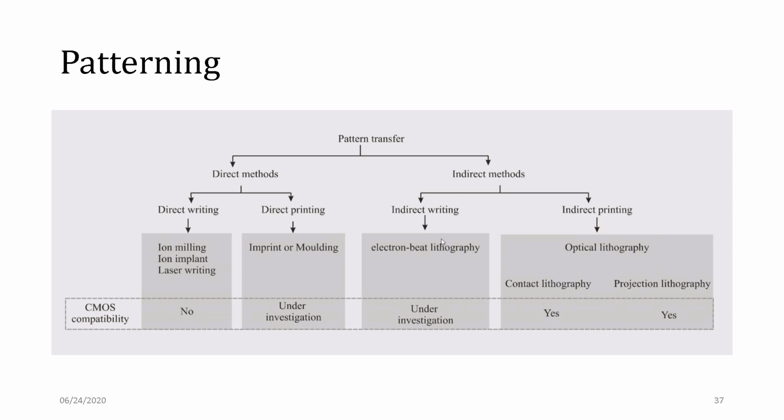In terms of CMOS compatibility, optical lithography is highly preferred, except that when you have fine features, it is resolution limited, which means you can't use this technique to draw fine features of say a few tens of nanometers. Even a few hundreds of nanometers is possible, but a few tens of nanometers is not possible with optical lithographic systems.